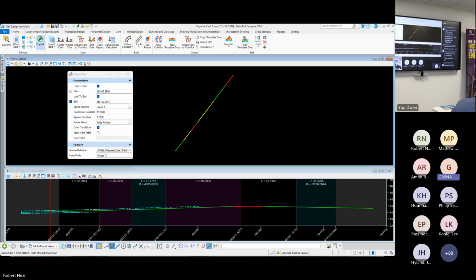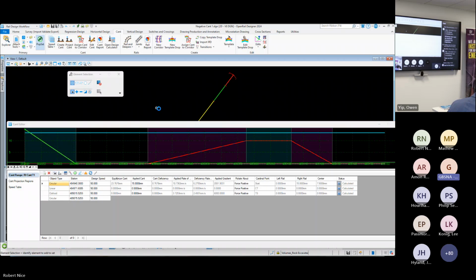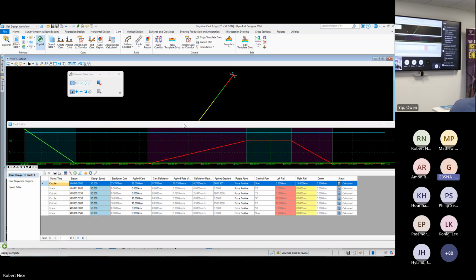But the most important bit is this false positive. We've got the usual suspects, inside, center, outside, but this false positive is what we need. Feature definition: you give these names in real words, feature definition, symbology, line color, line style, weight. But in anything you do in the new world, keep an eye on the names because they matter later on if you're doing reports from something to something else. Naming can be really important. So you pick the start, pick the end, you then basically left mouse click through prompts, and you get to this thing.